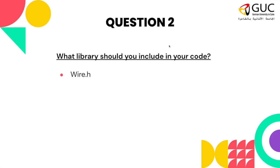So moving on to our first question: what library should you include in your code? We must include the Wire.h library. This is the library that implements the I2C protocol, or the two-wire interface protocol. Therefore, as we told you, it is implemented also at a software level, because we have this library that manages the entire communication.